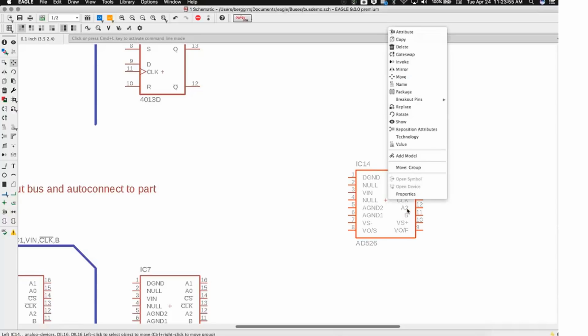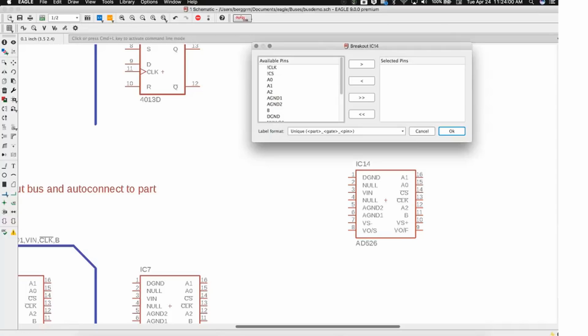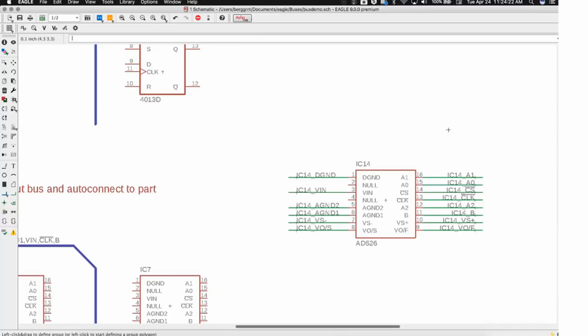And an opportunity also is here to select the specific pins that I want to break out. So I can organize the pins based on name, run down the list and say, hey, I'm going to grab everything which is here. Just run down the list here and grab these. And we'll go ahead and select my pins here, add my pins over here. And it'll go ahead and break out only those things that are relevant for that particular component.